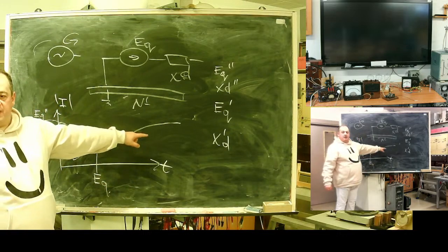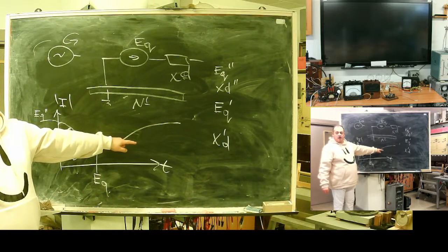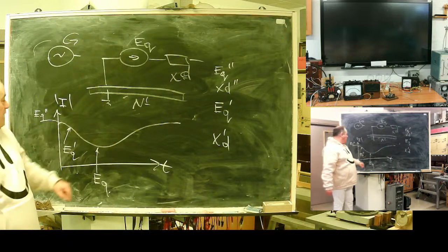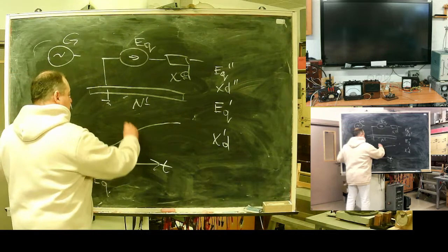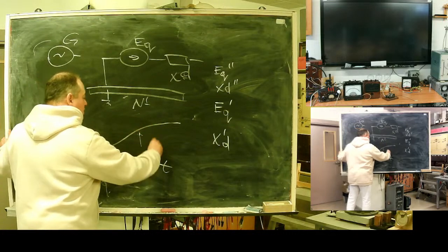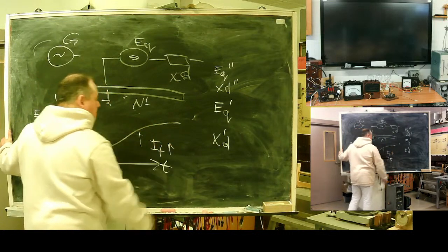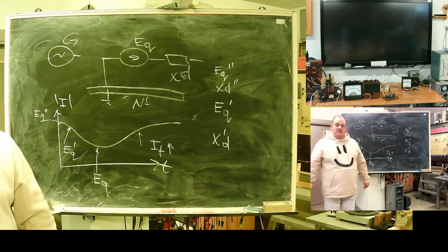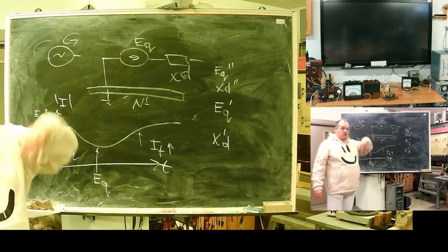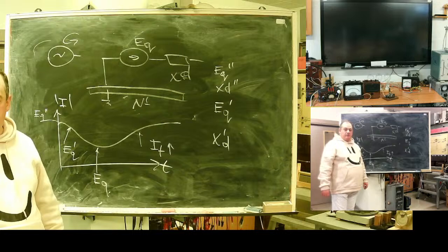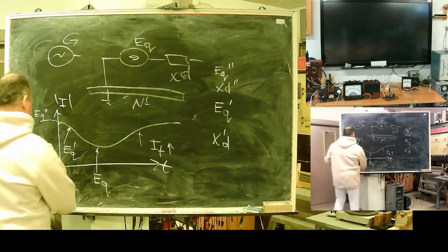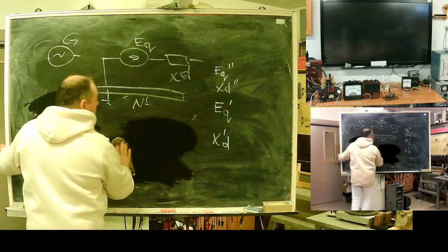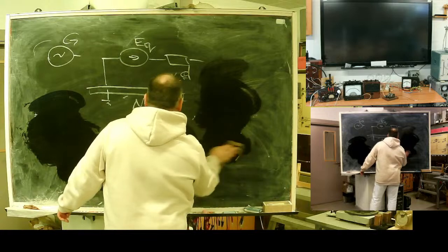Why does it go up? Because the voltage control system does not understand that it's a fault, and it will rise. So this rise is caused by the excitation system raising the exciting current. It will be a slow rise, if you do not timely clear the fault.